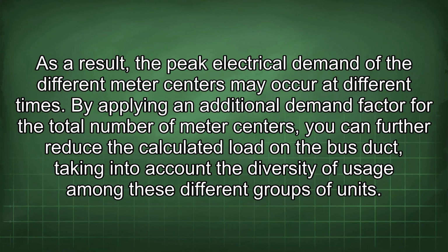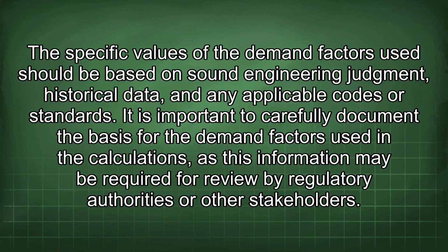By applying an additional demand factor for the total number of meter centers, you can further reduce the calculated load in the bus duct, taking into account the diversity of usage among these different groups of units. The specific values of the demand factors used should be based on sound engineering judgment, historical data, and any applicable codes or standards. It is important to carefully document the basis for the demand factors used in the calculations, as this information may be required for review by regulatory authorities or other stakeholders.